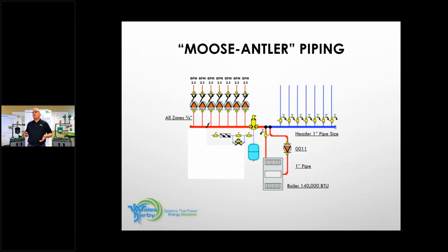All right, so if you look at this, the problem was not enough heat. Are we over pumping? Are we short cycling this boiler, or is the boiler not sized correctly? Well, if I look at the GPM that we gave you per zone, if you add that all up, I believe that's about 17.5 GPM. Remember, you can take your universal hydronics formula and do it backwards. I can multiply the GPM by 10,000. That would mean it's 175,000 BTU that we're trying to move if all circulators are running. My boiler is only 140,000. So is it over pumping or an undersized boiler?